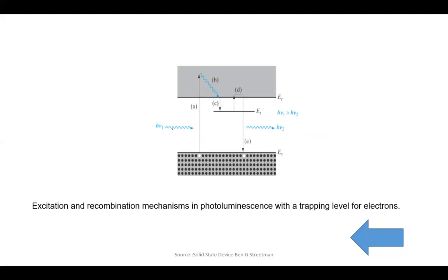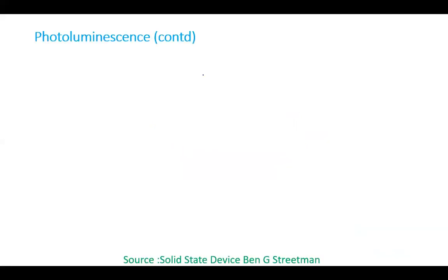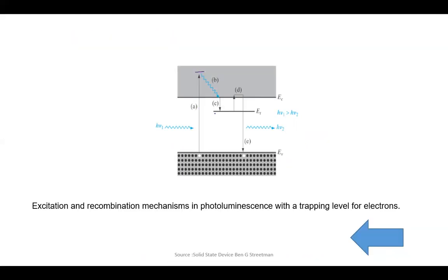So you provide a particular energy, the electron will be excited. Now it enters into this particular lattice. In this, it will lose some of the energy in the form of non-radiative losses, due to scattering events. Then it will come back from here to here, and it may radiate some energy or maybe not. Then it is trapped at this particular level, ET, and it is re-excited.